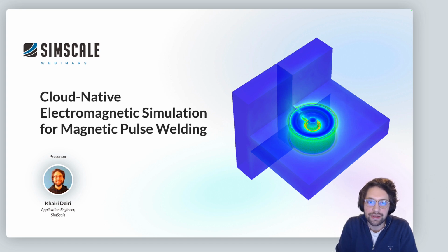And additionally, we will also investigate the radial air gap between the field shaper and the flyer tube, which in that scenario can also represent a little bit of the tooling, alignment, and misalignment during actual welding processes. The main results of interest that we are after in this case study are the flux density, the Lorentz forces, and the ohmic losses. With these, we can verify if a particular design meets the desired standards.